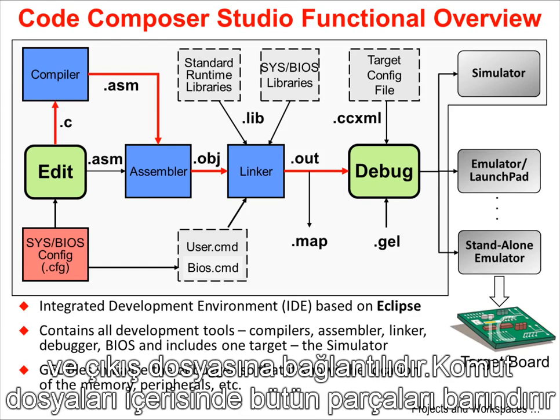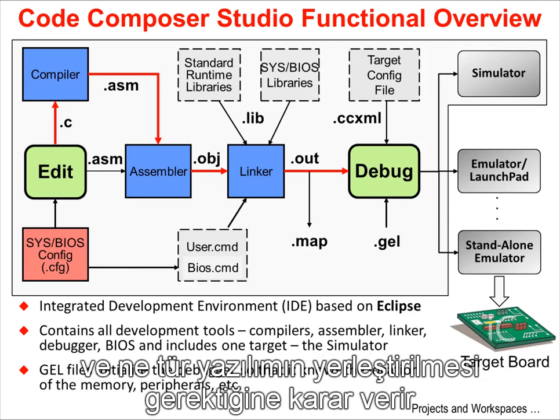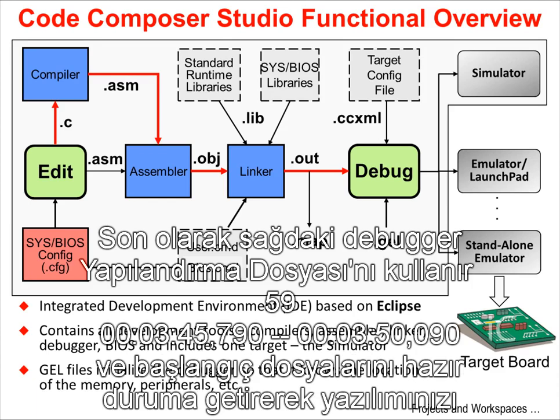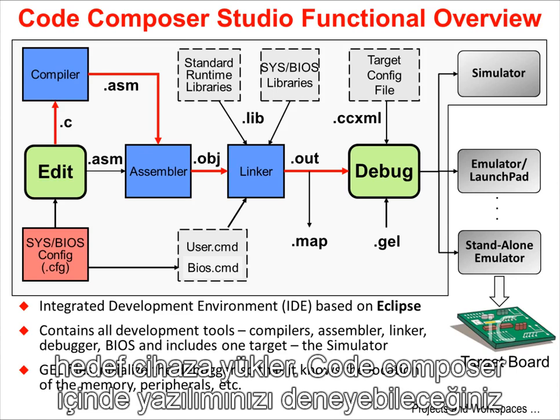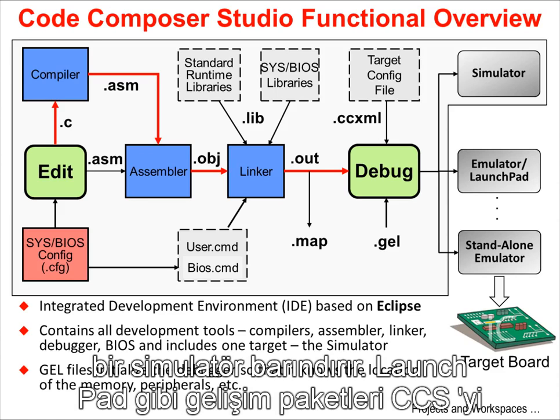The command file contains a list of all memories on the part and what types of software should be placed within them. Finally, the debugger on the right uses the target configuration file and GEL startup files to initialize and load your software onto your target device. Code Composer contains a simulator on which you can test your software.